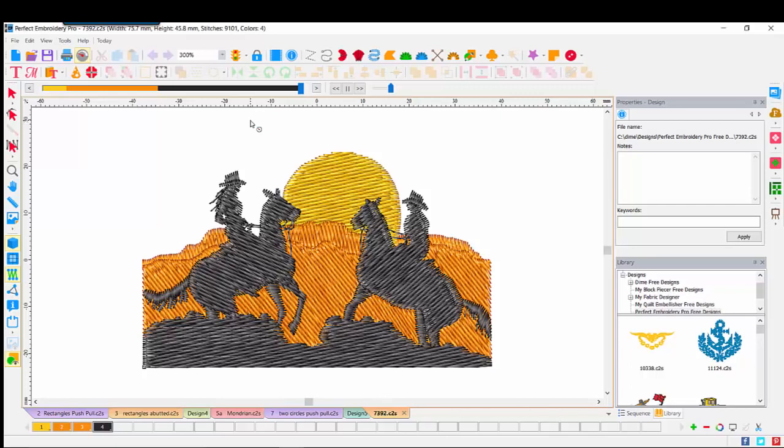We've seen a couple different samples with the horse and the circles that we played with earlier. The digitizer has used a pull compensation to avoid distortion. That, along with the position of our stop-start, those kinds of things, we can control the look of our design even after it's stitched out. So let's go about looking at dividing things into sections.